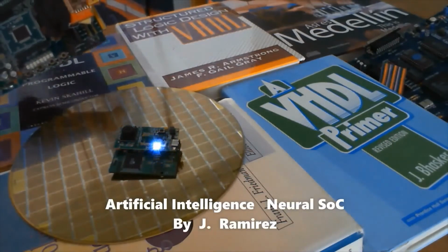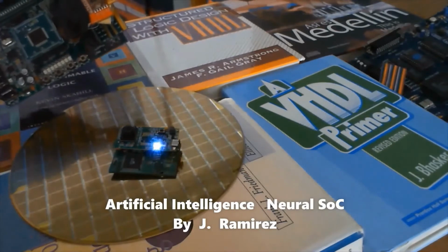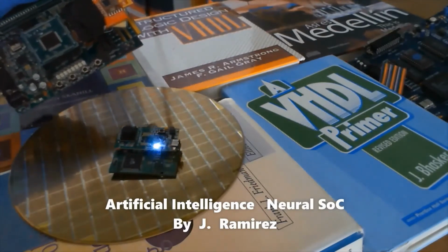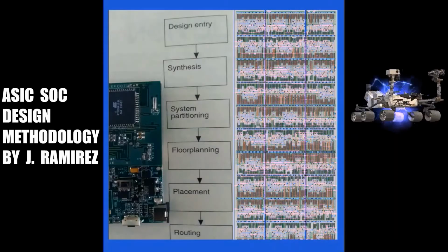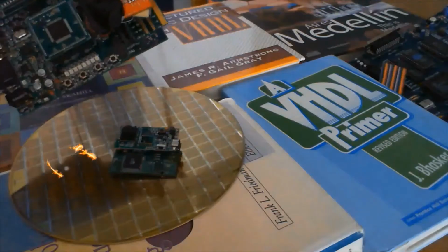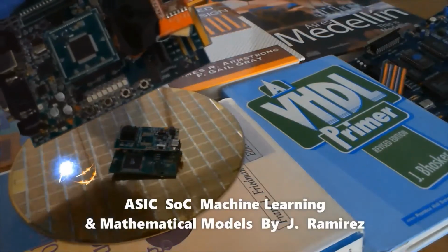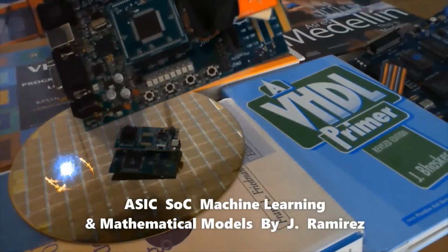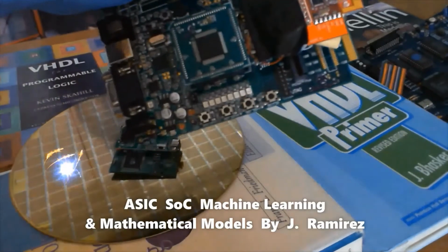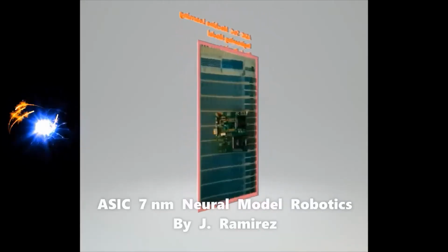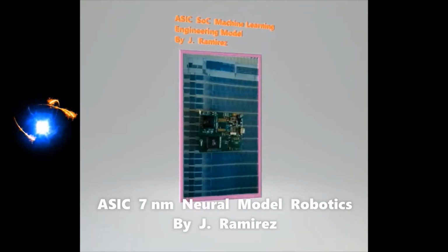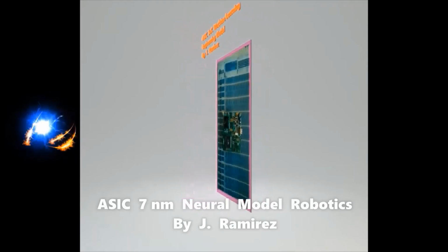My choice for synthesis and timing verification for this project was the Design Compiler. Two separate mappings were done. One mapping was performed during test insertion. The software model operated on a single clock. The timing model reflected the correct timing and load values for the actual LSSD macro.